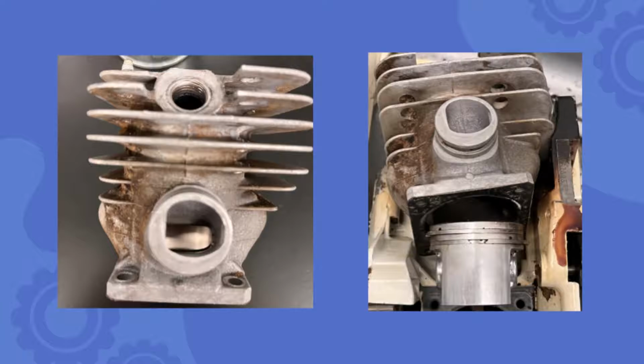The change in volume in the piston chamber during one rotation was determined by measuring the diameter of the cylinder body, then holding the piston in place and rotating the camshaft to find the maximum and minimum heights of the piston head, so we could find the changes in height and the effective maximum displacement of the engine.